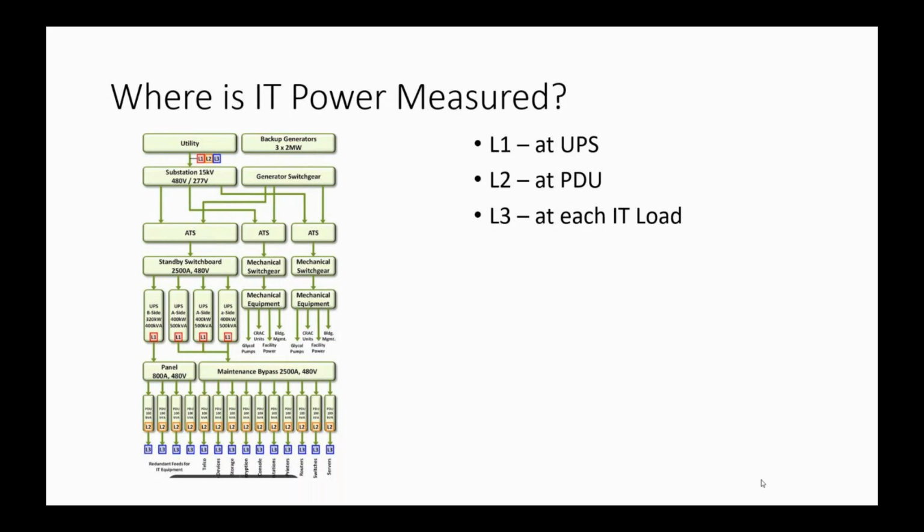But what's IT load and how do you measure IT load? There are different options. As the picture on the left shows, you could be measuring the power at the UPS that goes into the panel that feeds into all your IT data hall, right? You just measure that at one time, and that represents the measurement for the entire IT load.